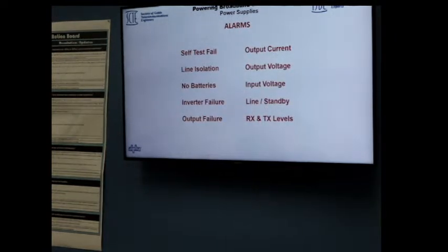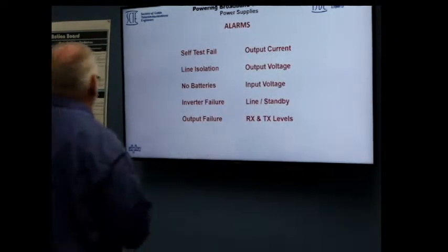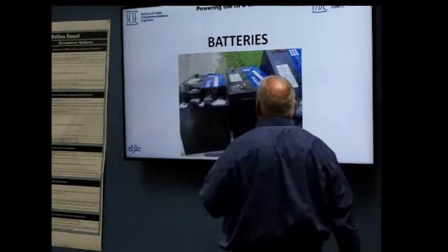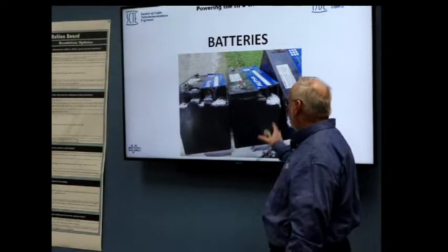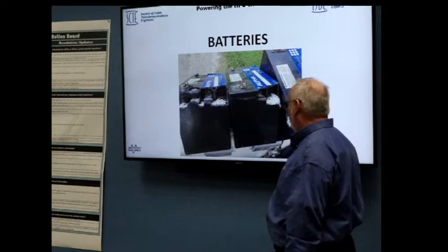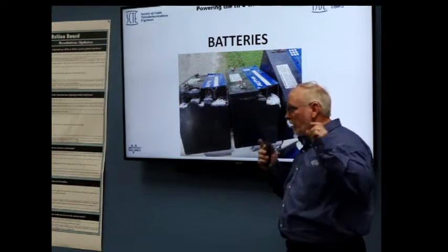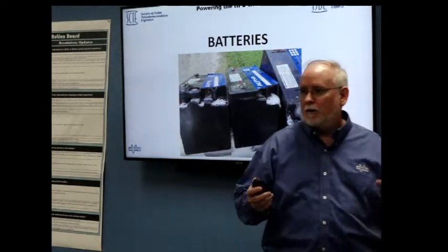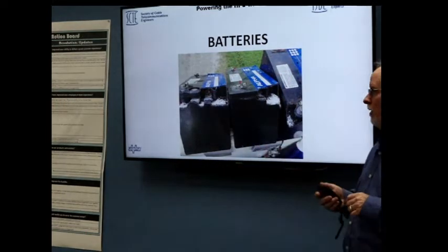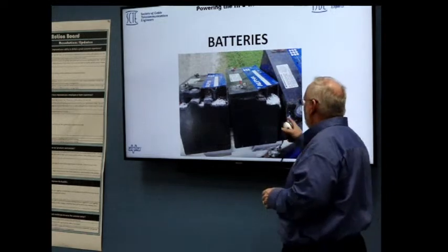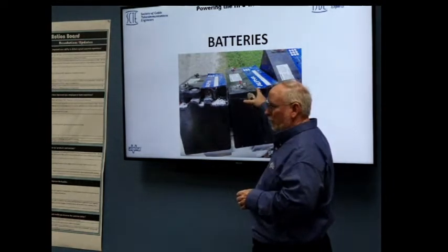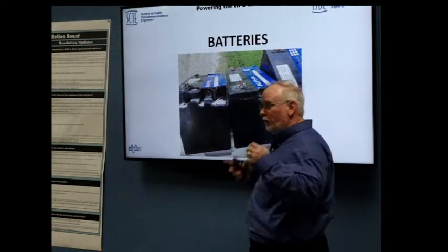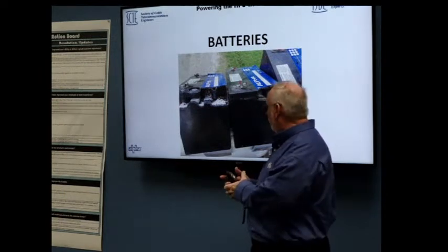Okay. I want to talk more about this a little bit because I have one section on that. Okay, batteries. You don't want your batteries to look like this, right? Most HFC powering is currently powered by lead acid batteries, LA batteries. They can be like these. These are actually called valve-regulated lead acid batteries. So any sealed battery is valve-regulated.